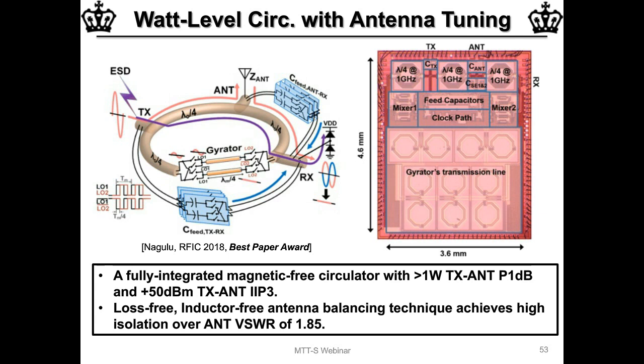This is a fully integrated circulator, everything in CMOS. A lot of the loss comes from these passive components. You see a bunch of spiral inductors here on this die. For a lot of those spiral inductors, you can use technologies like integrated passive devices, some extra back-end-of-the-line thick metal layers above the chip. There are ways to lower the loss of those. It's a relatively new field. We've been working very actively on it, but if you think about the first circulator that we demonstrated, it was almost just 3 years ago. So it's only been 3 years that we've been hammering away at this. We're definitely trying to bridge the gap in performance, but offer functionalities that are uniquely enabled by having these circulators on chip.